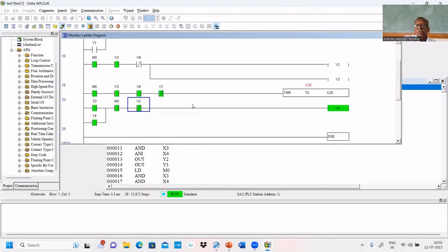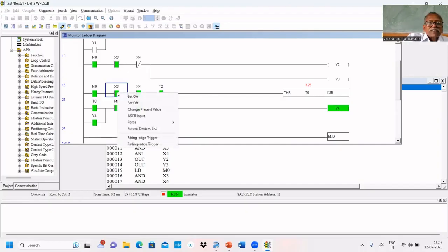What happens here? After a delay, the outlet valve is opened now. Outlet valve is opened. Now it is draining. We have to imagine like that. Now the tank is draining. First, what will happen? First X3 becomes 0. So we have to change that first.